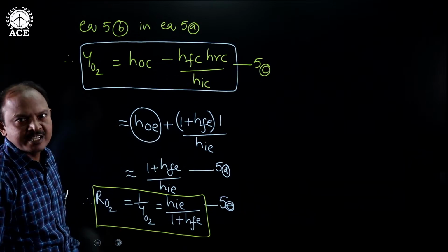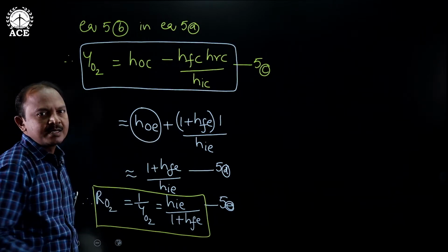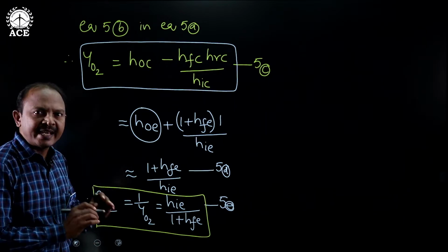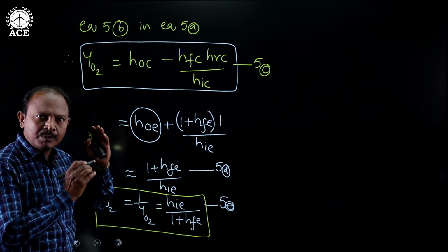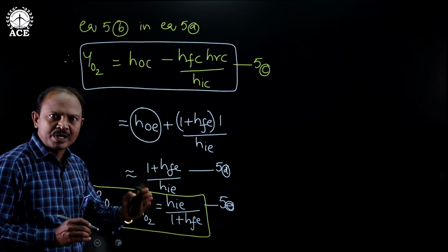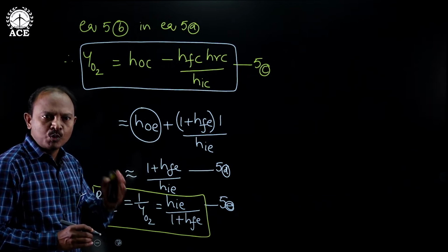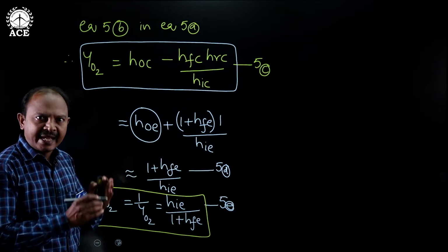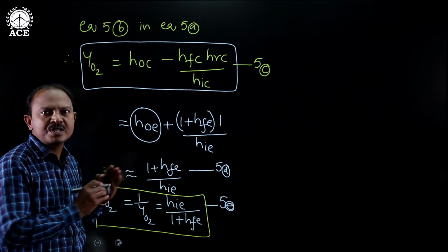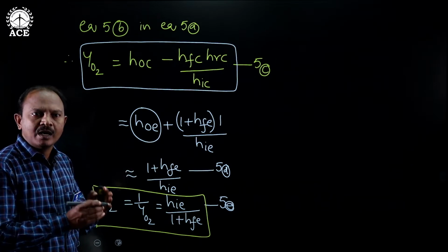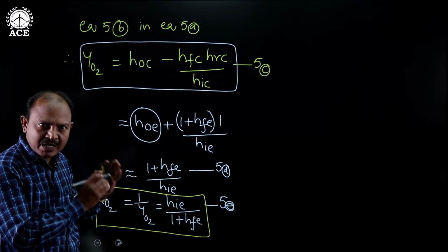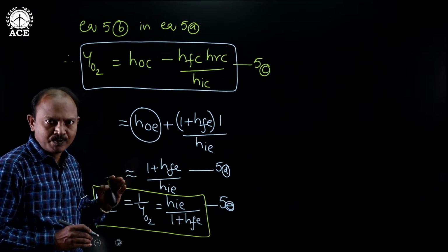This is the equation for output resistance in second stage CC amplifier. With this, we have completed the analysis of current gain, input resistance, voltage gain, output resistance, which are the four reference parameters in stage 2. Exactly by following the same procedure, we have to estimate all these four parameters again in stage 1. That is the work we are supposed to do in case 2.